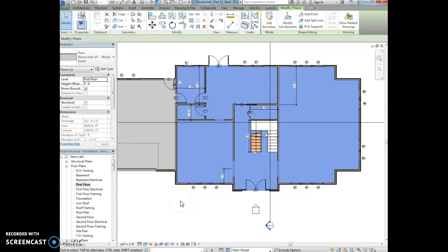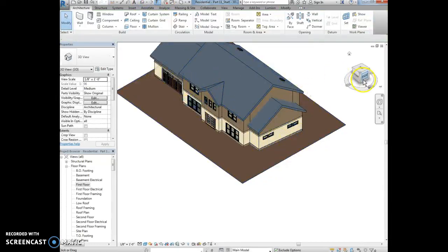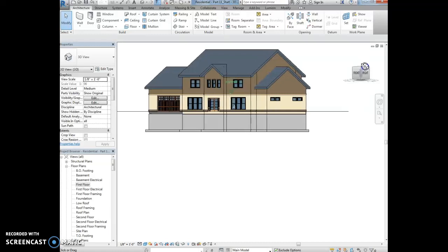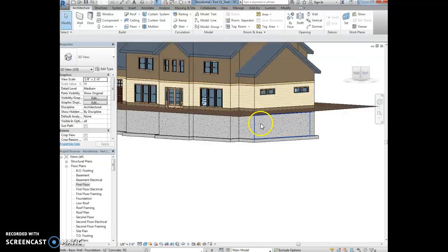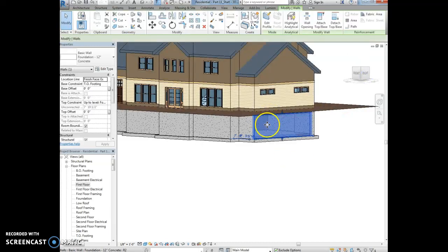So now let's talk about the items under the floor. What's holding up the building? So I'm going to look at this in 3D, and I'm going to tip my building up for you just a little bit. So what you guys will have are something called stem walls. So you'll have concrete walls under here, and they will be approximately, let's say, like 4 feet for the height of a crawl space. So to create these walls, I'll show you how to do it in just a minute.